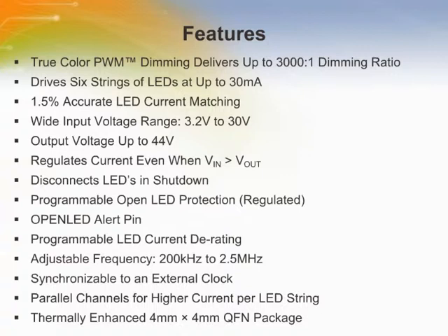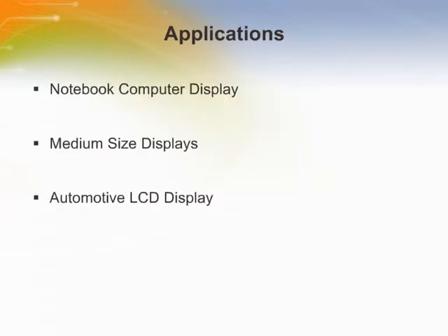Its thermally enhanced 4mm by 4mm QFN package offers a very compact solution footprint for LED backlighting applications. Its multi-channel capability makes it ideal for medium-sized, thin-film transistor LCD backlight applications. Its input voltage range of 3 volts to 30 volts makes it ideal for automotive and industrial applications.